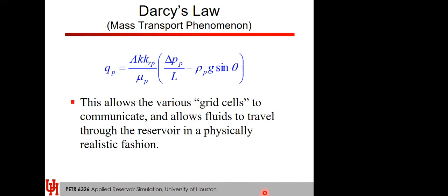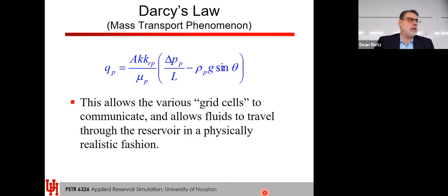If the values like pressure or compressibility are associated with the grid blocks? Yes. Compressibility is a term we have, but it's not necessarily an individual grid block value. But the compressibility will affect the porosity of that grid block. So porosity is an individual grid block value, and it will be impacted by the compressibility and the change in pressure. We will know the compressibility. Okay, what about pressure? Yeah, so for each grid block we have a value of pressure, which I'm going to show you in a minute when we get to the equations.